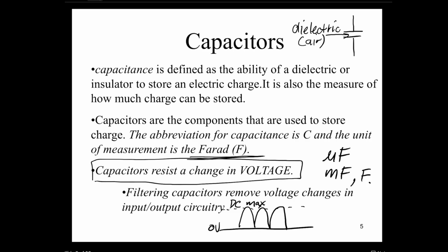What's the job of the capacitor? Well, you bring in a capacitor that resists these big changes, or delta voltage values, and you can smooth it out. And the more capacitance you have, the more you can smooth this out to give you a near perfect DC voltage, right? So that's the idea. It takes large fluctuations and turns it into a nice, flat, steady DC value.